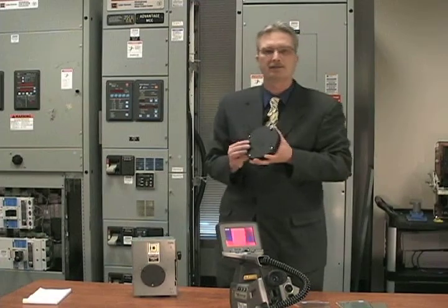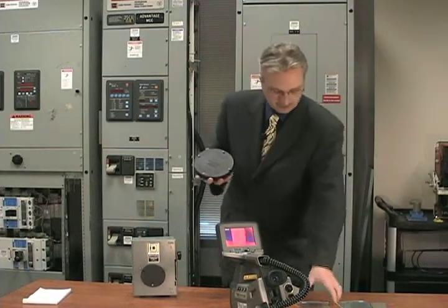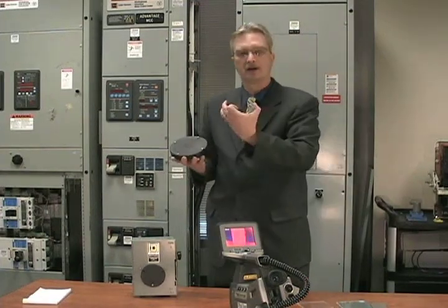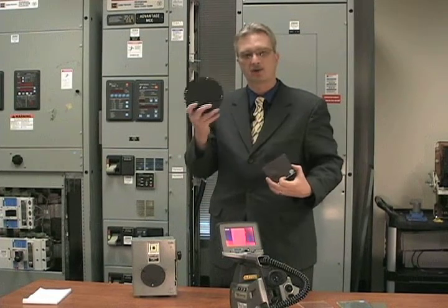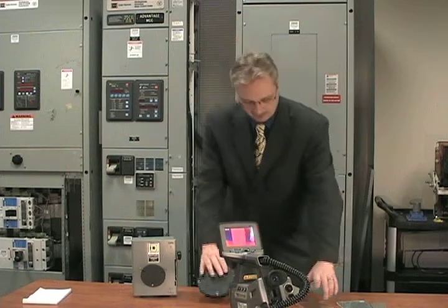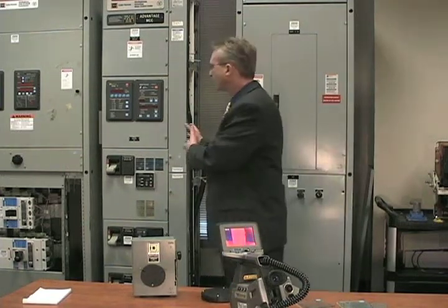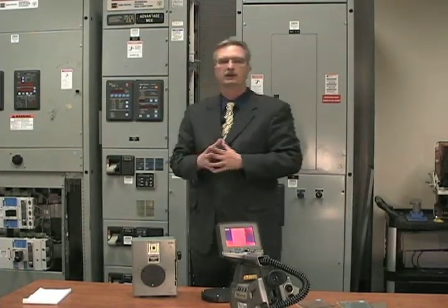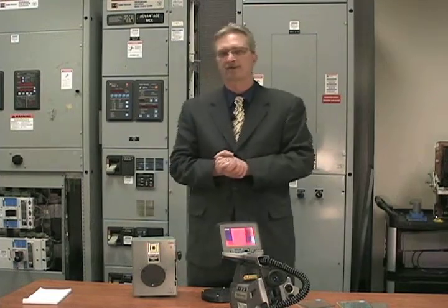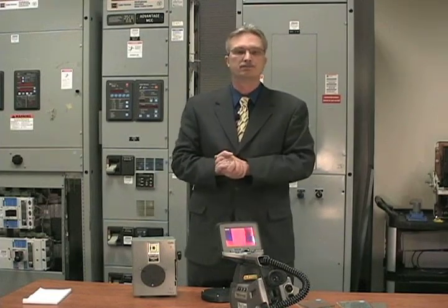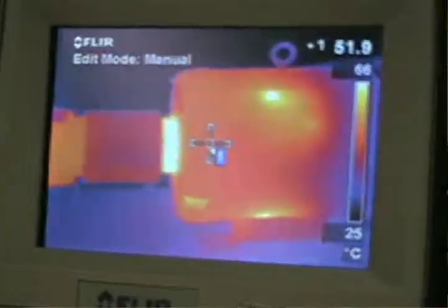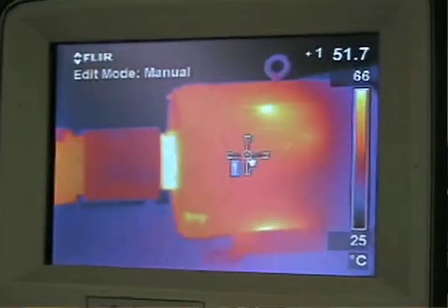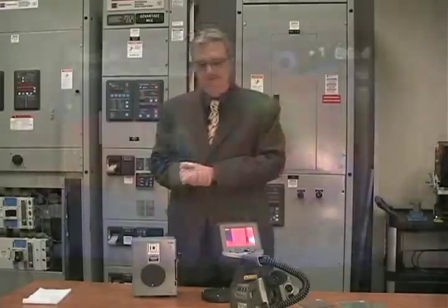We'll talk more about an infrared window in section 3, but as we already saw, a piece of glass is not going to allow the infrared camera to see into the switchgear. Therefore, we have to use special materials. But energized electrical switchgear is one of the biggest applications on the planet right now for infrared. Another application is motors and their associated driven equipment, like a fan or a pump, anything that has bearings or warm areas, just to see if a bearing is overheating, for instance.